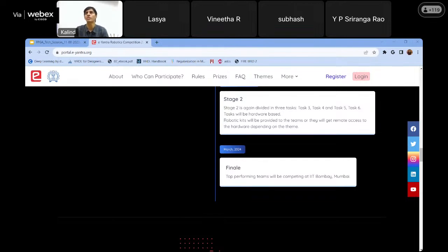It depends on how many logic elements your logic design requires. Different FPGA boards available in the market have different numbers of logic elements, basically the number of CLBs that I talked about. So that's what I mean by logic elements. There are FPGA boards ranging from, let's say, 5K logic elements up to 56K, and more than that as well.